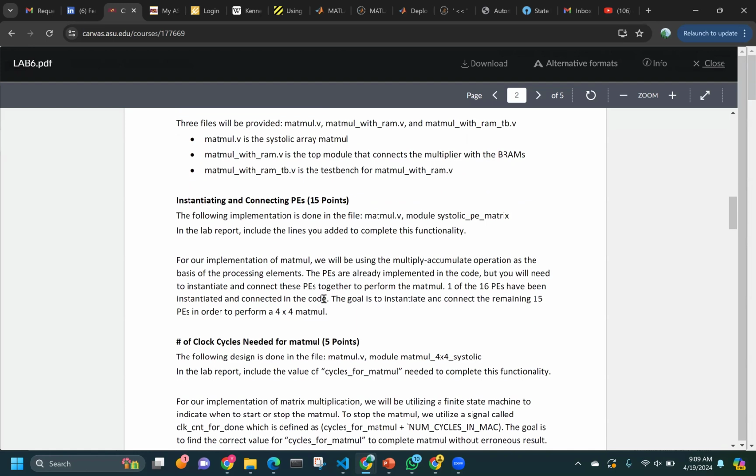As I was telling you, there are PEs which are connected in a mesh fashion. You can see that in a 2D mesh, one PE would be connected to its 4 neighbors, each in north, south, east, and west direction. Those connections are through wires, and those wires are output from one PE or the preceding PE and an input to the next PE. So you have to carefully instantiate your PEs so that you can show the connection, which two PEs are connected and in what fashion.